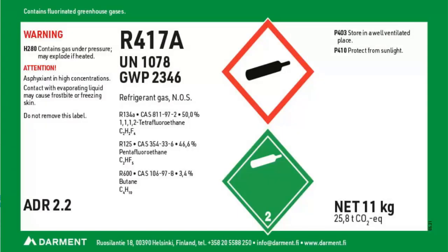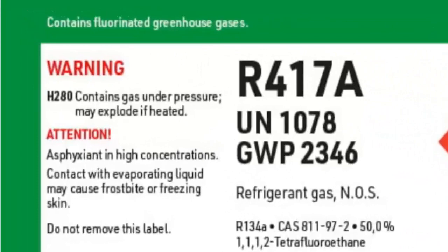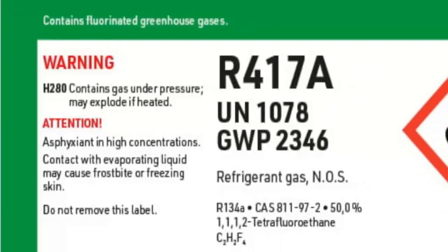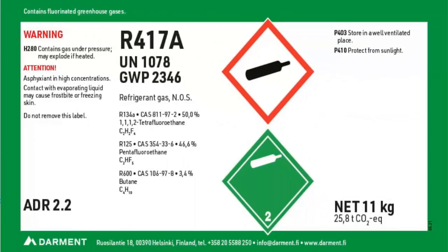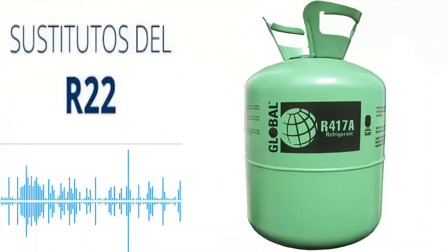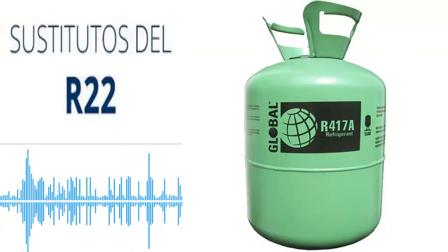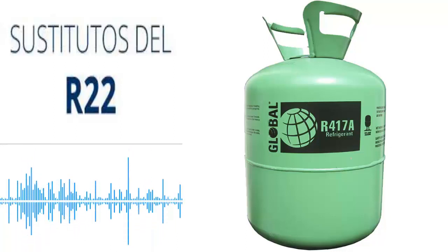The global warming potential of the R-417A is 2,346. Perhaps it is its main enemy because it already begins to have environmental restrictions in those areas where the GWP has to be less than 1,500. Another notable advantage of the R-417A is that it has a low discharge temperature compared to the R-22, which is very good for the compressor. See you then in the next class of this course on refrigerants.